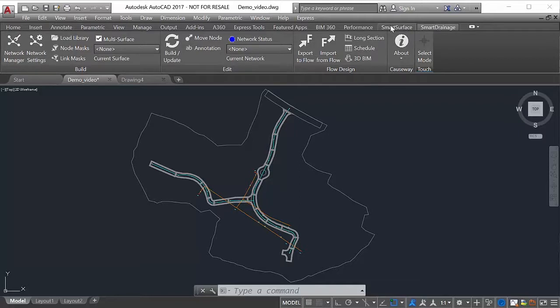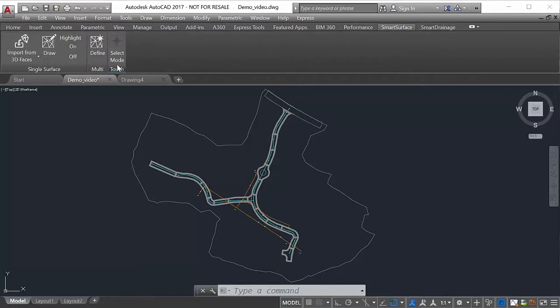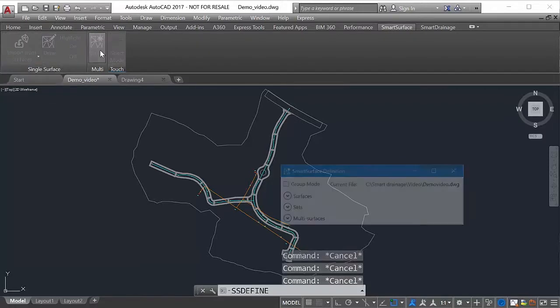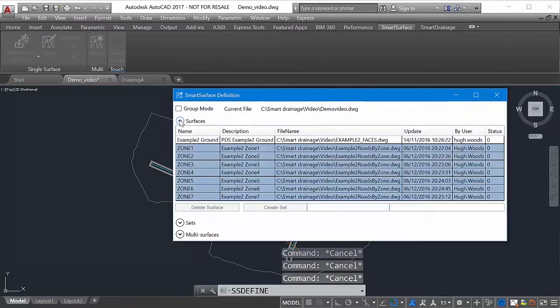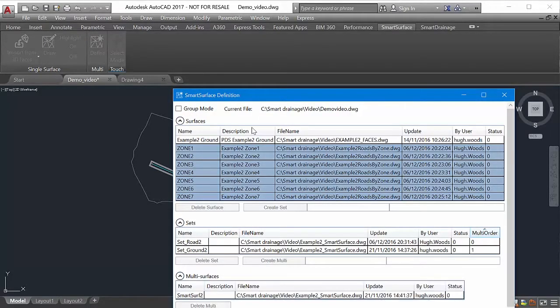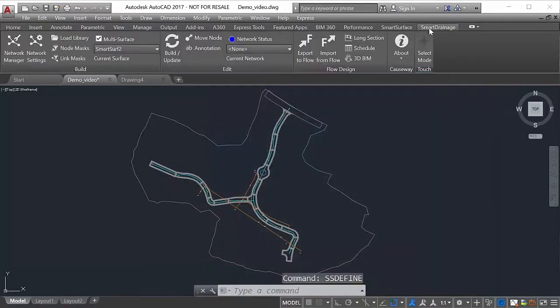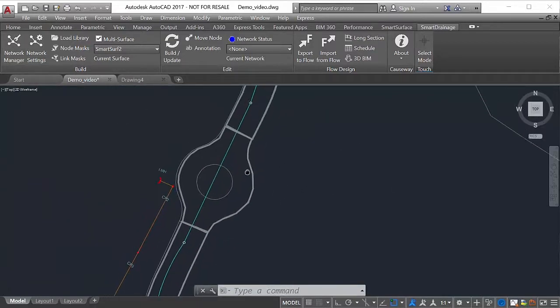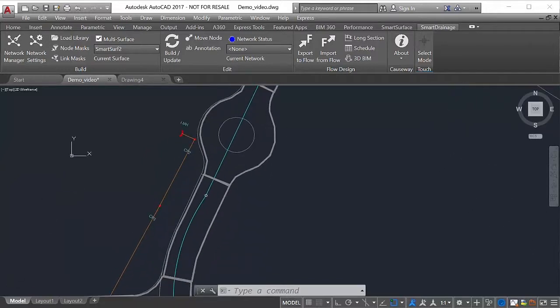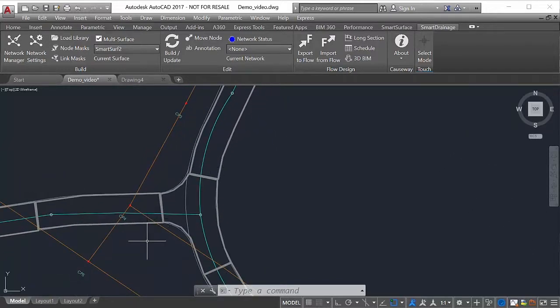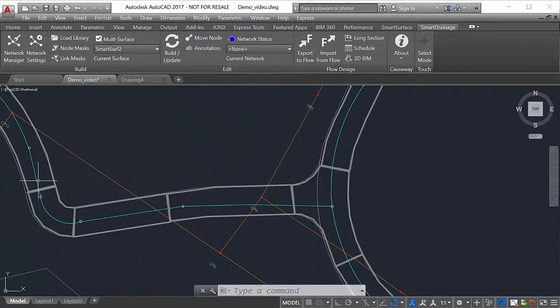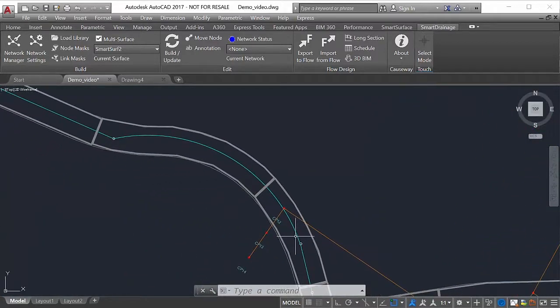Smart Drainage is a smart tool that will automatically translate a plan view of a drainage layout constructed from standard AutoCAD graphic entities into a network of nodes and links ready for Causeway Flow to design and analyze. The network may be drawn specifically for design with Flow, or as a project drawing, or maybe a legacy CAD drawing. Smart Drainage is very versatile in interpreting the CAD structure of drawings. The user has only to select the outfall node of the CAD drainage layout to translate it into a Flow network.